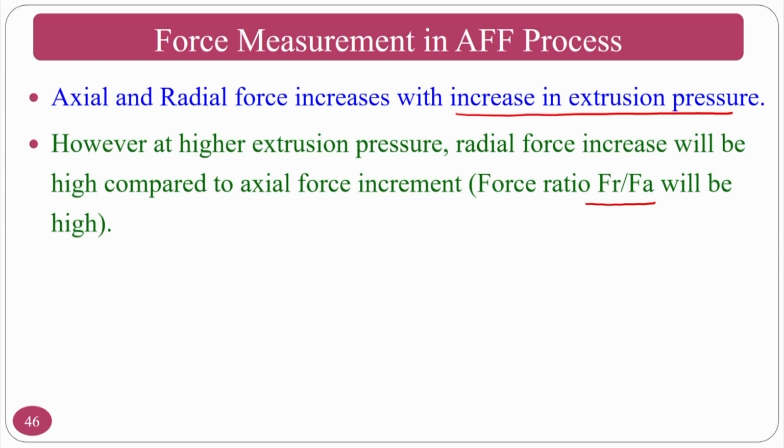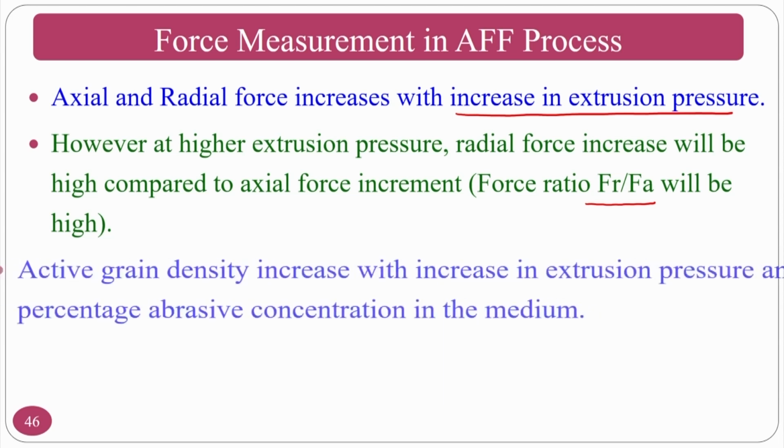If that is the case, the problem in the abrasive flow finishing process is that your indentation is high compared to your axial force. You may have an axial force slightly higher, but it cannot move the abrasive particle in the axial direction because the indentation depth is tremendously high compared to lower forces.